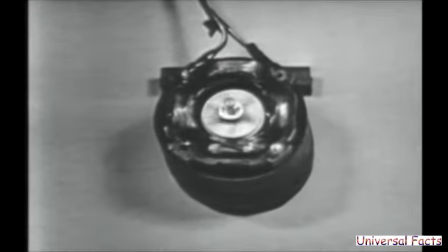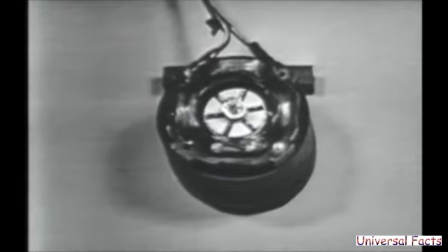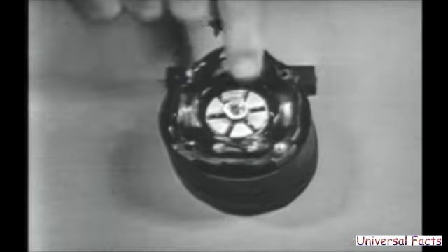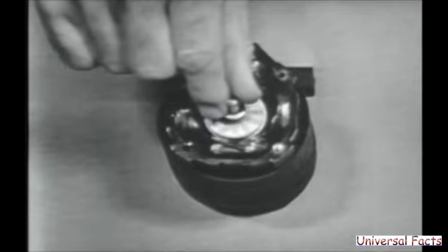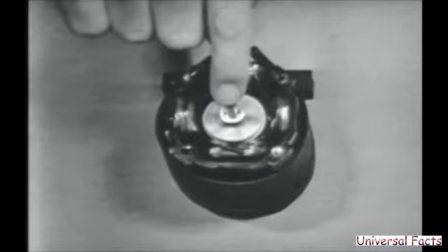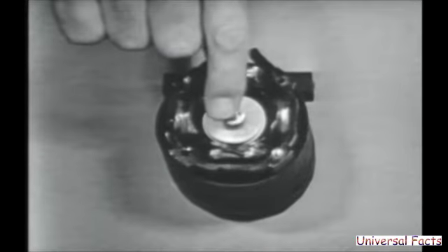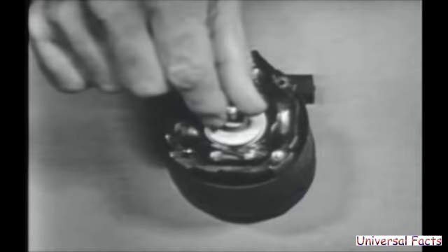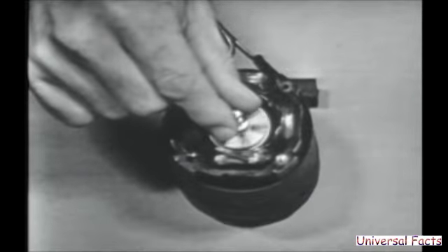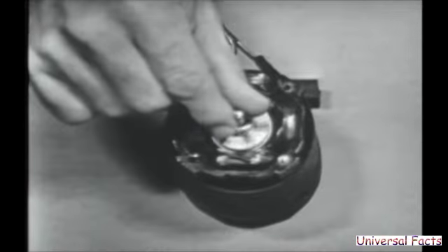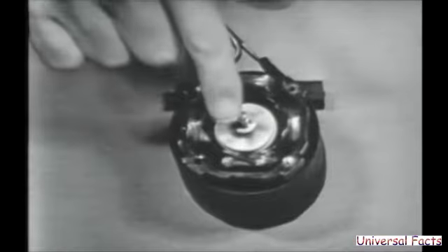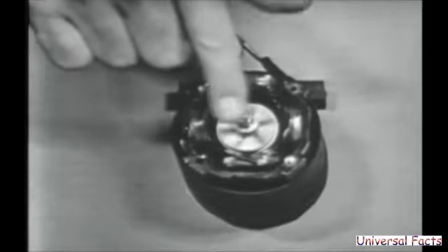Which brings us to item 5, which I believe you can have. Exactly. All right, the rotor of the induction motor does not rotate as fast as the magnetic field because of several forces that act on the rotor. One, the internal load, that is rotor weight, the little fan, the bearing friction, and so on, and the external load on the motor, such as the gears, pulleys, or the fan blade, or in this case, my finger. As I squeeze it a little bit, you can see that it turns slower. Right. Whatever work the motor must do. So the rotor's got to go slower than the rotating magnetic field in order to have relative motion so that it can become an electromagnet.